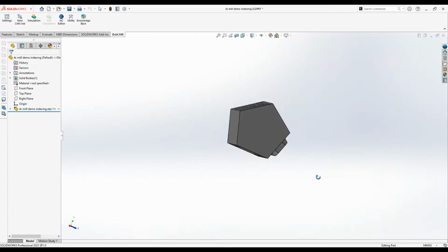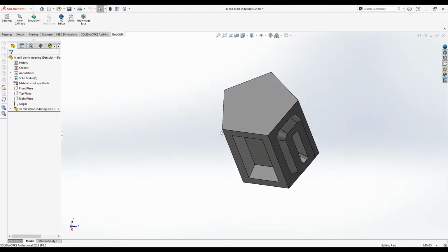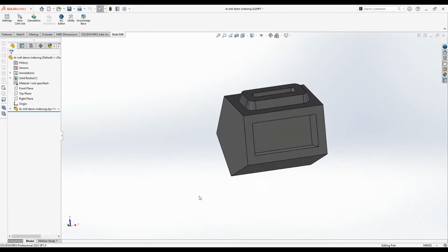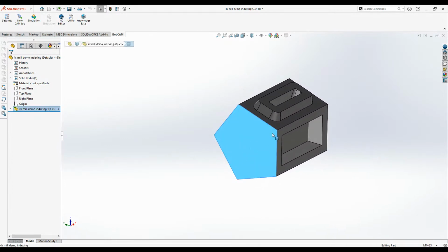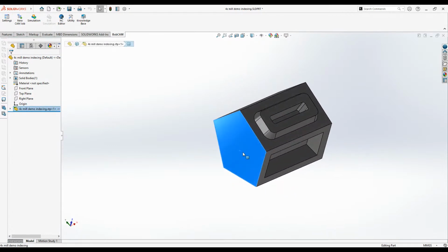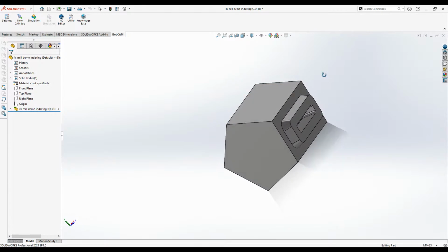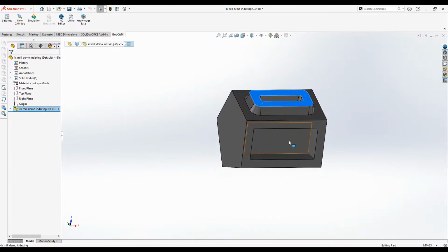All right, so we have a part here with 5 different sides that will need to be milled with kind of a cylindrical shape here, you could say, and the x-axis of rotation will be going through this surface here. We'll be setting it up with an a-axis rotation. So we'll probably want to start with a facing operation on this side. Then we'll be doing the 3-axis roughing, facing and pocketing on this side, and going all the way around.